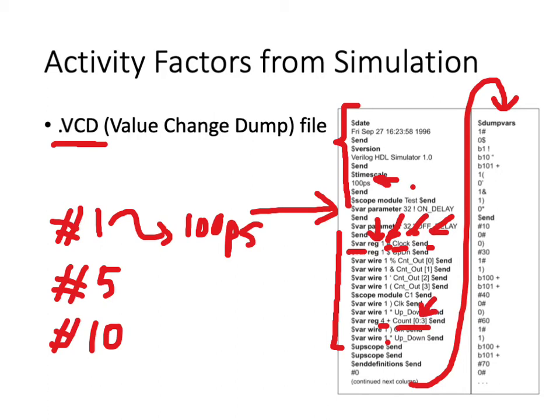The final section of the .vcd file, the most interesting section, is the section after the $dumpvars command. This is where the value of each and every net defined in this region is recorded. Only changes, and the time at which those changes occur, are recorded in a .vcd file.